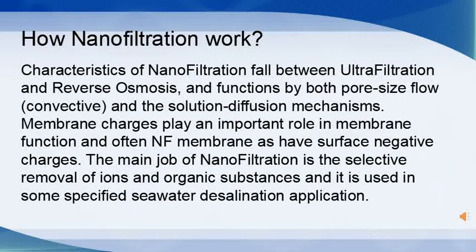How does nanofiltration work? The characteristics of nanofiltration fall between ultrafiltration and reverse osmosis, and it functions by both pore size flow and solution diffusion mechanisms. Membrane charges play an important role in membrane function, and often nanofiltration membranes have negative surface charges.